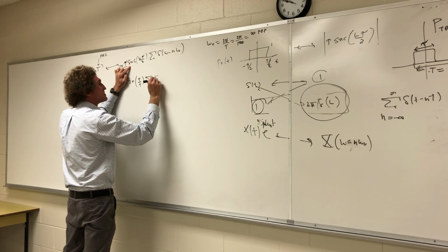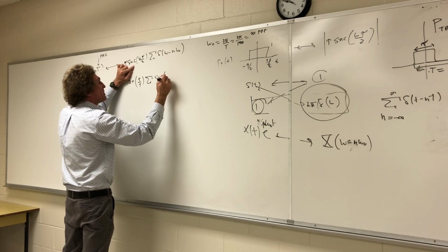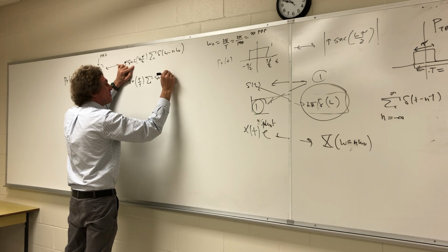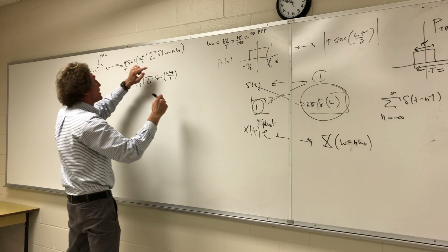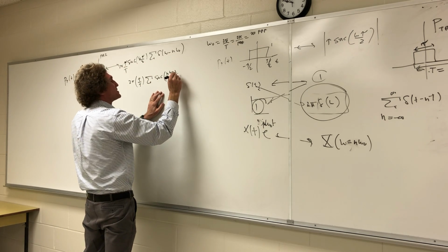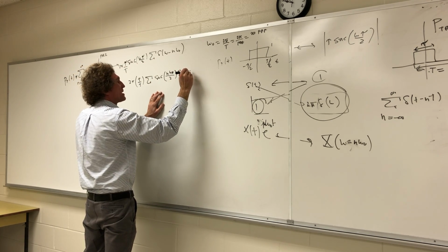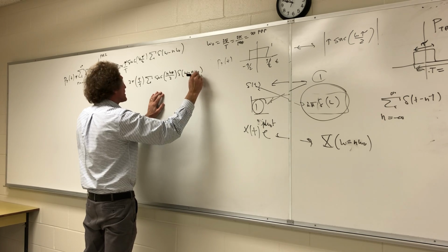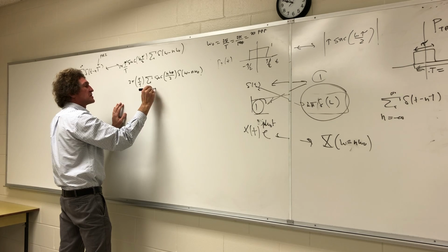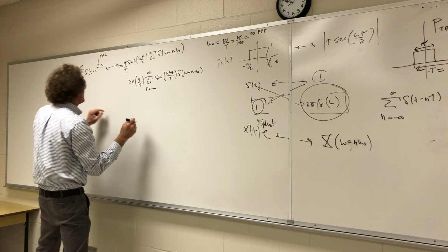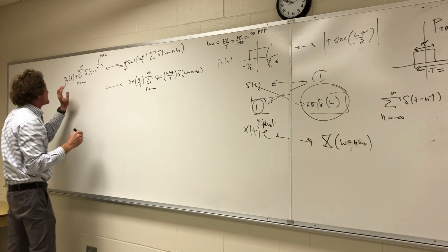and now I can take this infinite series, and now I'm going to have the sinc of n omega naught over 2, and then I'm going to have times delta of omega minus n omega naught here, and I left it in terms of n. N goes from minus infinity to infinity, and that is the Fourier transform of this signal.